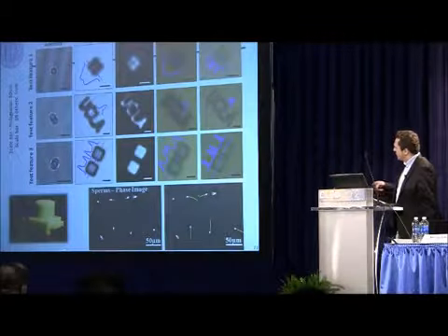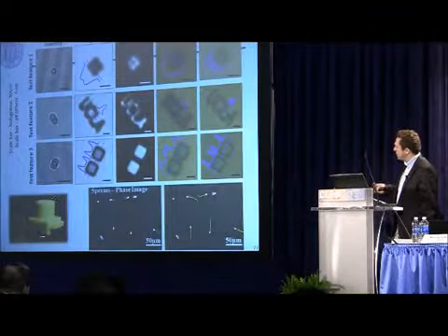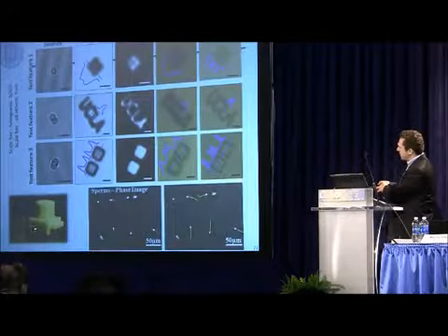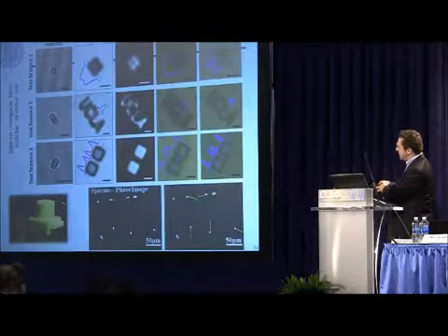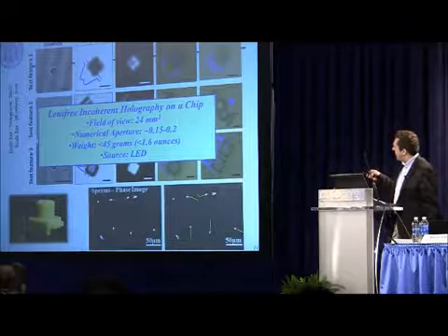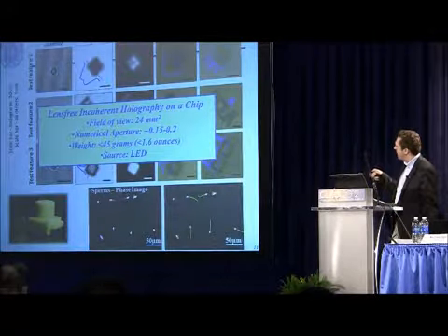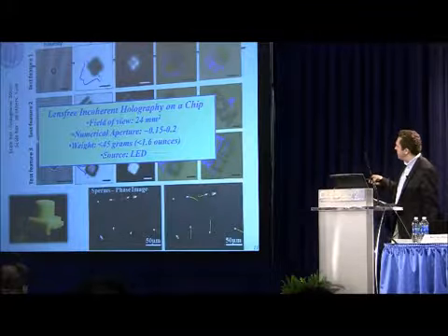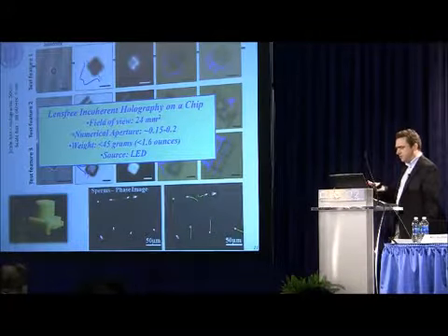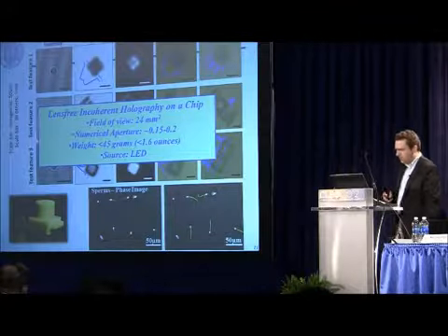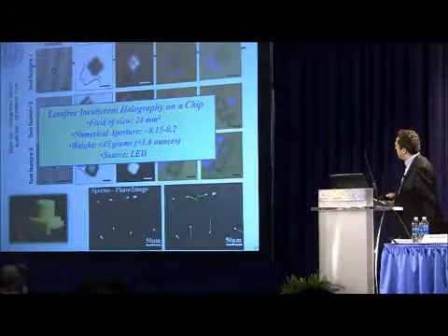So what I've shown you so far was a basic module which used a single light-emitting diode here, and the cells were inserted so that you can get a very compact microscope which can look at a very large field of view. To give you some numbers, the imaging area is around 24 millimeters square, and the numerical aperture is around 0.15, which gives you a sufficient resolution around 1.5 microns to look at subcellular features of white blood cells and other parasites.